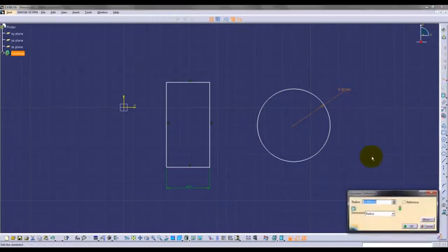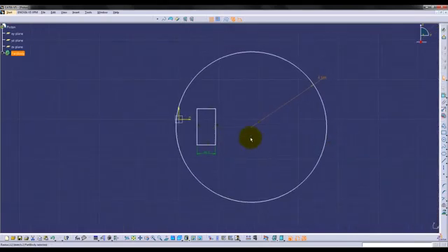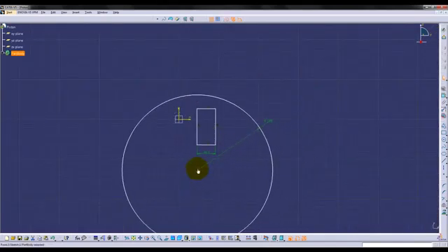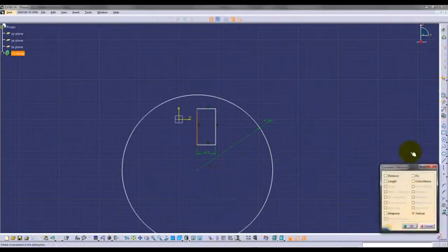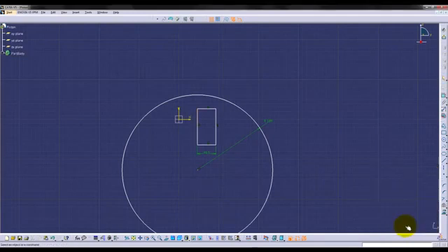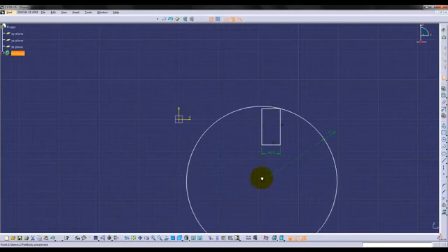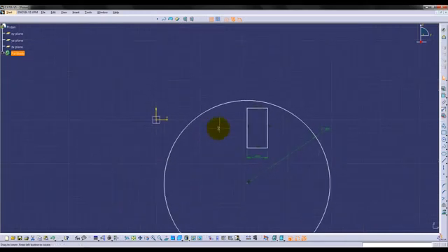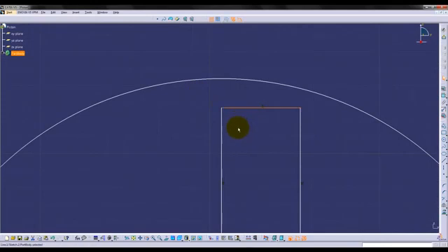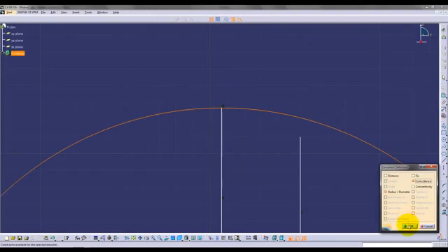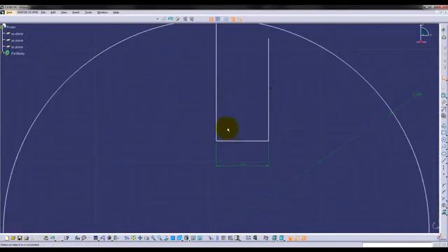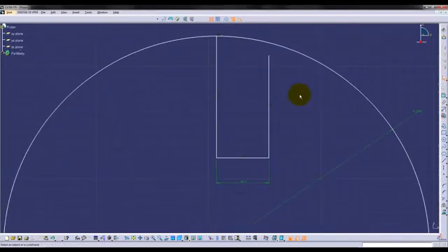Then, place a very large circle in your sketch and set the radius to 189 millimeters. Apply the coincidence constraint on the center of the circle to the left vertical segment of the rectangle. Seen here is how the coincidence to the left segment of the rectangle keeps the circle locked on that axis. Then, constrain the edge of the circle to the top left and right corners of the rectangle. This will, in effect, create the curved surface of the top of the piston.